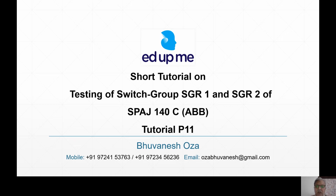Then we went to switch group SGB, that is switch group blocking, which was a very important switch group in which you can do reverse interlocking, you can do temporary blocking of the relay. That means if the downstream relay senses the fault, you can send the blocking signal to the upstream relay so that it does not operate, because it is not required to operate. The downstream relay has sensed.